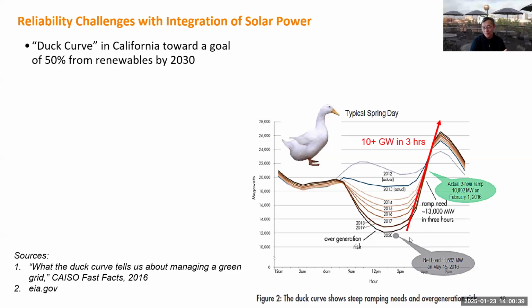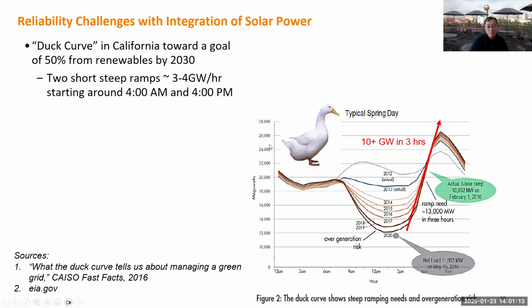You need to have a lot of energy storage, because energy storage can respond much faster than the conventional generator. Or you can have a lot of spinning reserve. By spinning reserve, I mean conventional generators that are running all the time but not generating electricity. When you need their power, they will just increase their generation immediately, which means you still keep those generators in the grid. Okay.